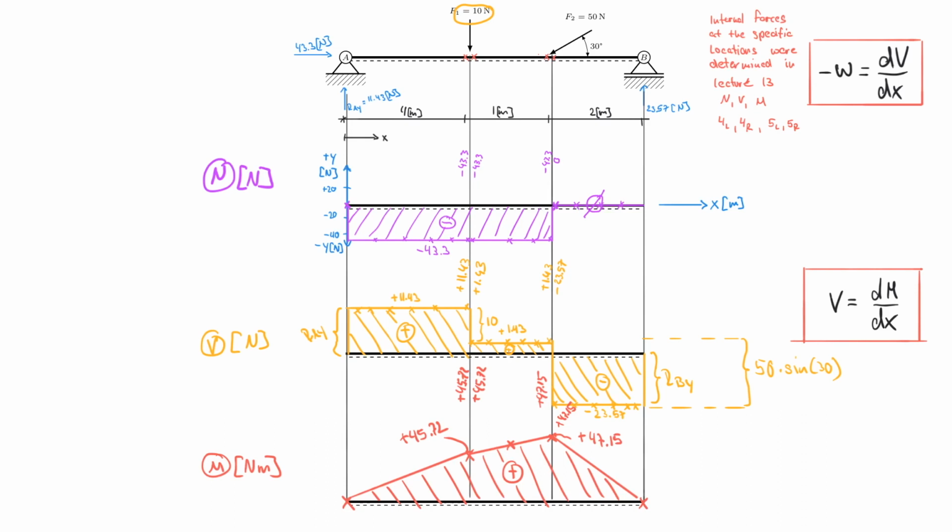But this is very important for us to understand, and we clearly understand that there's a mathematical relationship between the load case and the shear force diagram, and there's a relationship between the shear force diagram and the moment diagram. You could, of course, do that the other way around, and you could state that the moment function is really the integration of the shear force function.